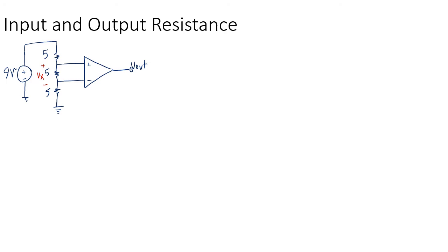So if I do this, now remember when I wanted to actually measure a voltage across a resistor with a voltmeter, the most important feature of the voltmeter that I mentioned was that its internal resistance has to be infinity. Why? Because if the internal resistance, imagine that this is like the entire thing here, I'm going to replace it with the resistor, right?